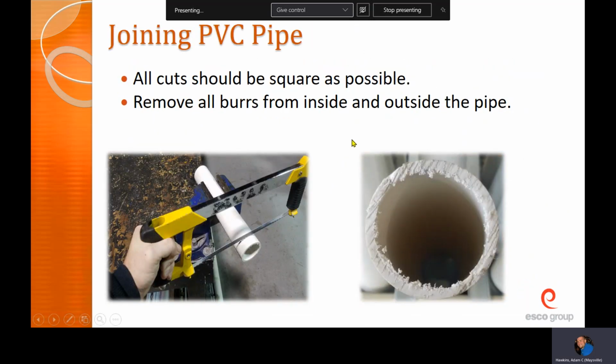So you have to take into account your elbows because your elbows count. They restrict a lot. So in that case, what I ended up having to do was upsize. I had to get my 2-inch pipe so far up and then expand it to 3-inch, so that 3-inch pipe has a lot more room to move that air, so it reduces my back pressure a lot. So always refer to the specs.